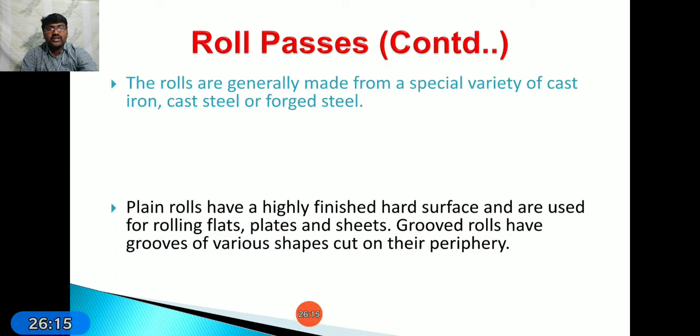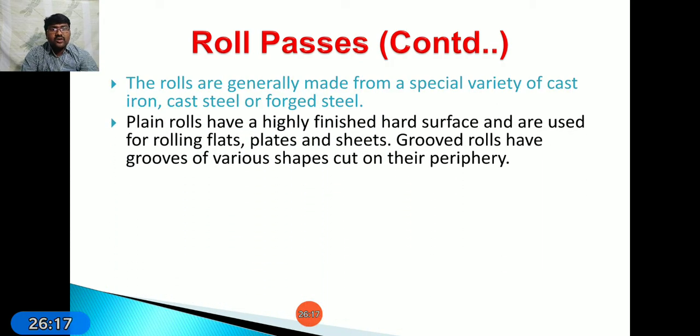Next, plain rolls have a highly finished hard surface and are used for rolling flats, plates, sheets. For that case we have to use a high surface finish. Next, coming to grooved rollers, they have grooves of various shapes cut on the periphery of the rolling surface. Based on that we have to prepare the size and shape of the groove, as per the required shape.